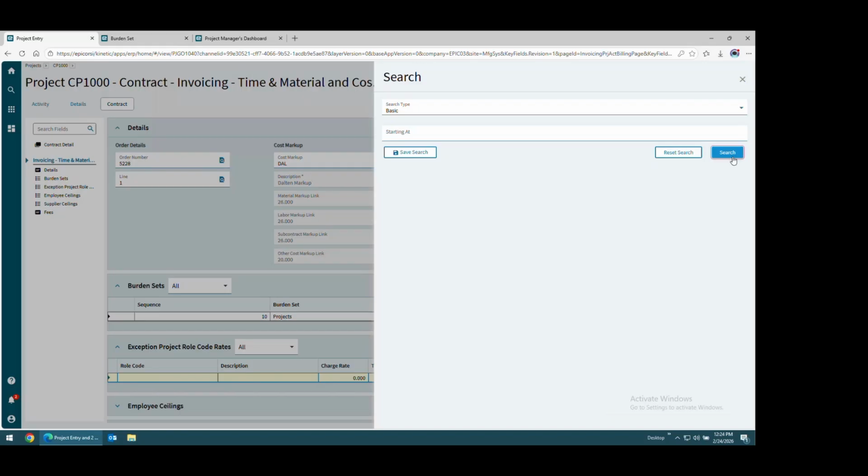I'll pull up my dashboard here, and we can use our ADD 100 project as well. So if we look at our CPI section, we already have a phase here that has been 100% completed. We have a couple more phases there with some partial percentages of completion. What all the system is doing here is doing that math for us, right? We know what the planned cost was for those activities. Based on the percent of the work that we've done so far, this is what we should have incurred, and then it's comparing that to our actual. So that's how it's coming up with that performance factor.